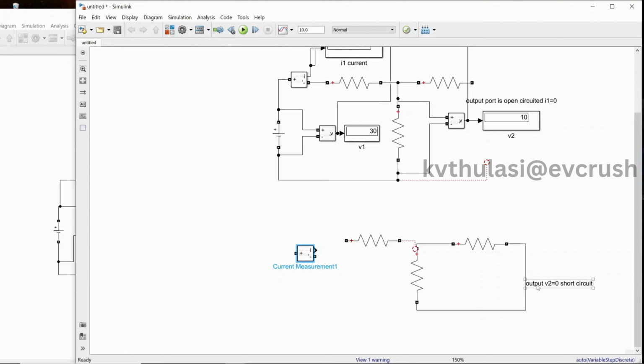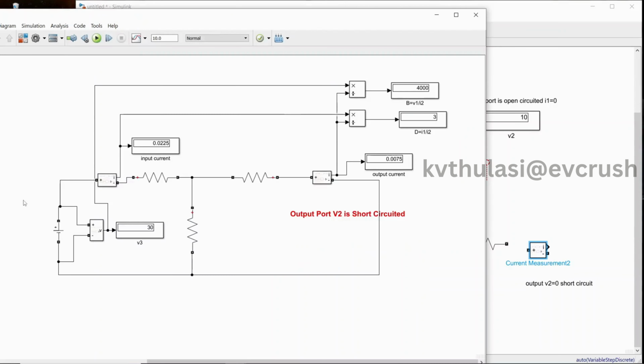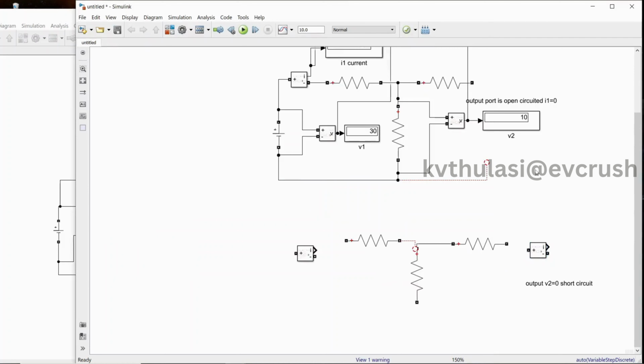Here also you require the current, therefore we'll remove this link and find the current with Control C as well as Control V. We require I1 and I2, you can see here I1 and I2. Connect this to this one, connect the short circuit through an ammeter, and negative to 0. Now this block is completed.